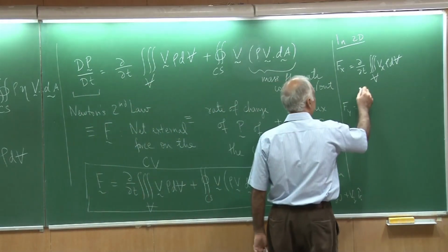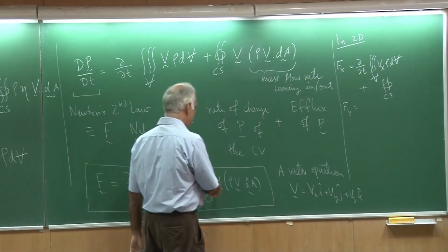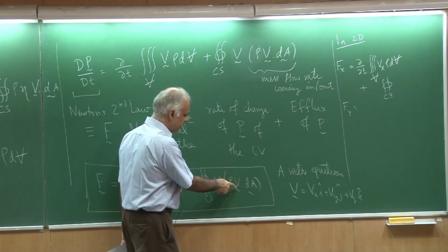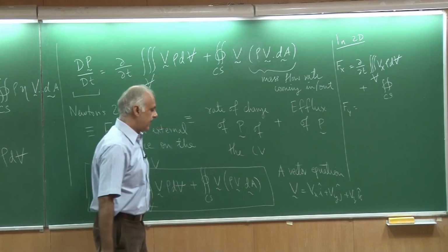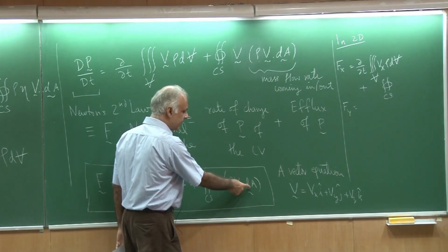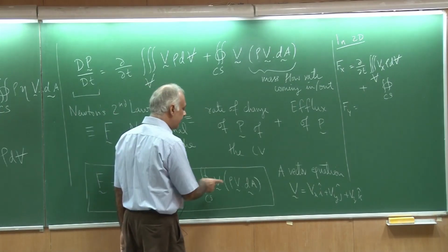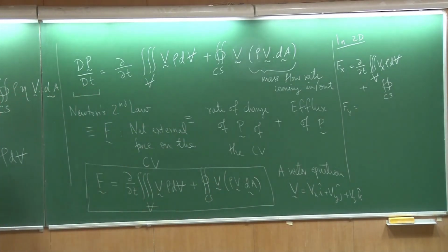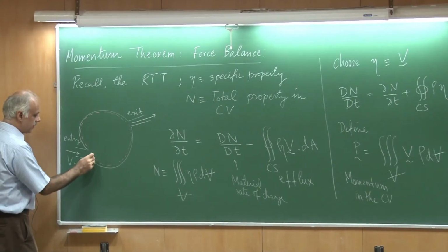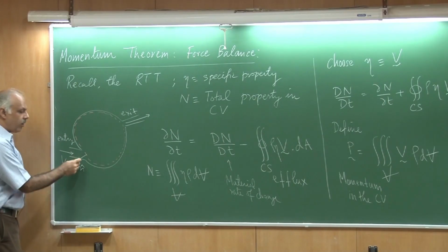So therefore, this V is simply the Vx. The second term would be the control surface I need to integrate, and I am going to leave this as is because this is the dot product between the velocity and the control surface area. Remember, this was the area with a direction and the unit normal is supposed to be pointing outwards. At the inlet port, this is my inlet velocity and my unit normal is opposite.